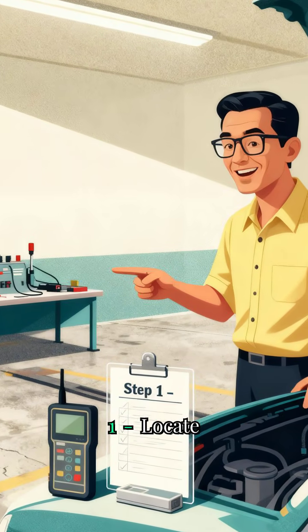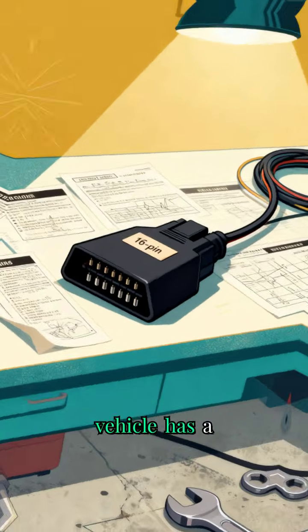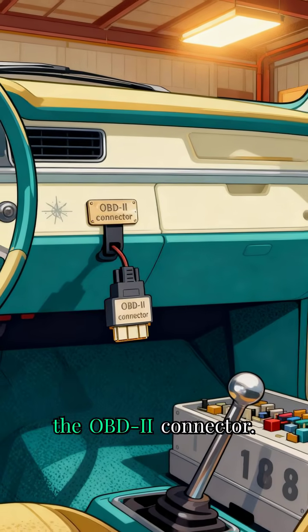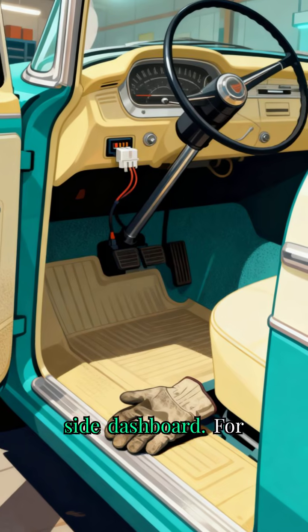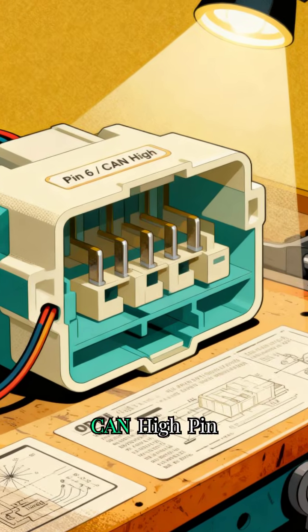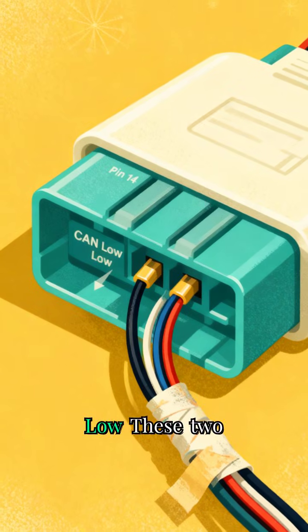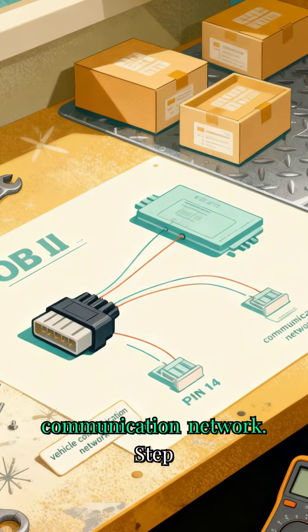Step 1. Locate the data link connector. Every modern vehicle has a 16-pin data link connector, also called the OBD2 connector. It's usually located under the driver's side dashboard. For high-speed CAN, the two pins you'll be testing are pin 6, or CAN high, and pin 14, or CAN low. These two pins connect directly to the vehicle's communication network.